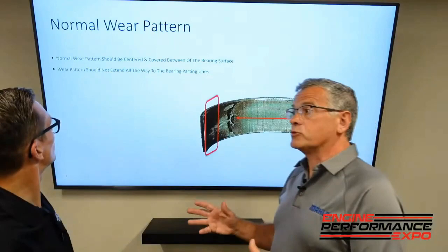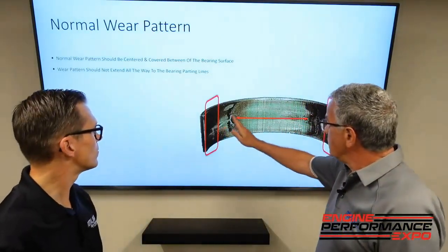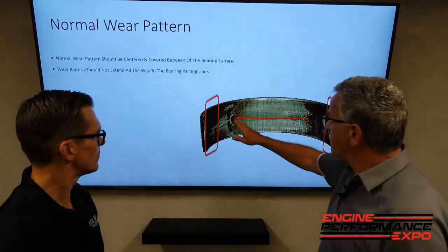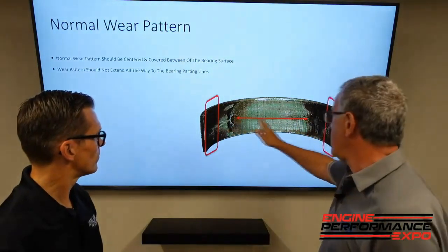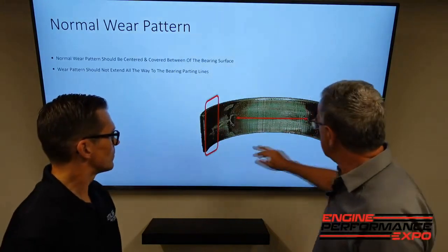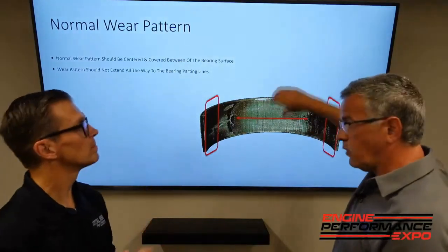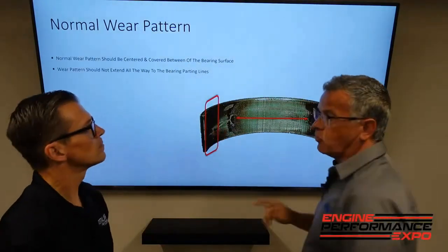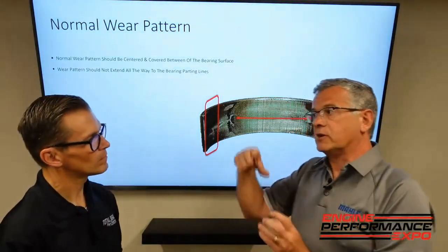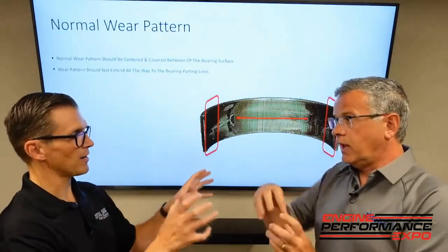Before we get into what's wrong, let's talk about what's right. Typically, with an upper rod bearing, you will have wear on about two-thirds of it. Just a nice universal. The area circled here has eccentricity, which creates that wedge. That's the relief area. And then at the very end, there's bore relief, which covers cap shift or deformation in a connecting rod, because as it fires, the load goes through and it lets it have an oval area for compensation.